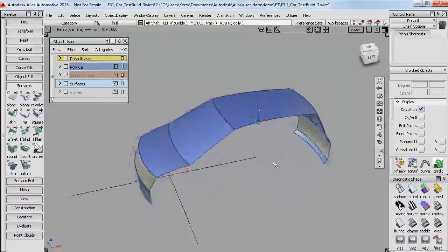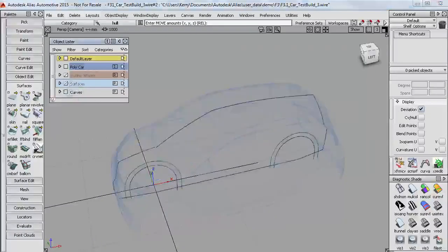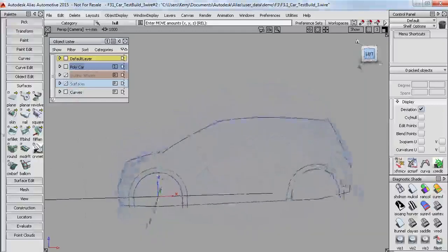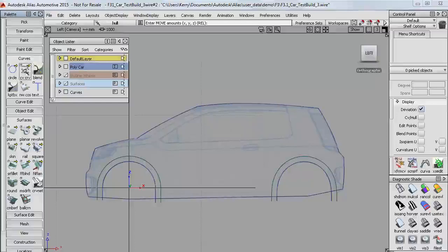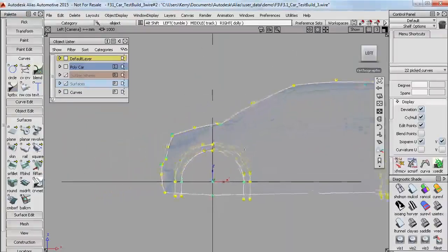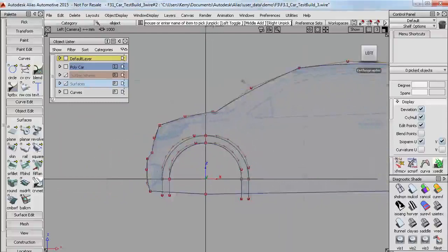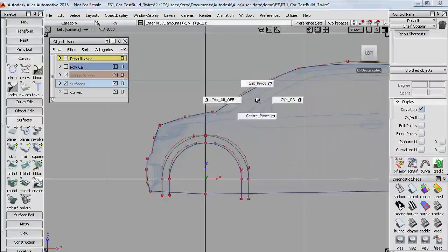But instead of doing that, I switch from creating surfaces and show you the curve tools in Alias. When we create these centerline curves using the tools on the Curves palette, all of these are NURBS curves, so we just use the same techniques. Displaying the CVs and picking and moving them to shape the curves. But I also use these to explain some of the underlying theory, which you can find in the first 2 theory builders on the website.